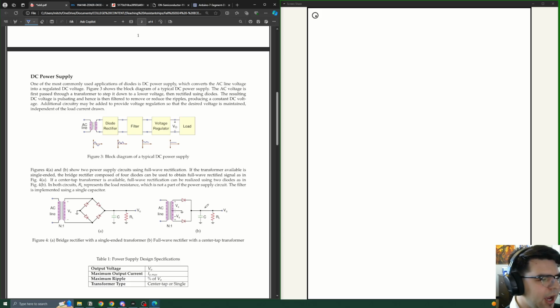And then we also have a center tapped transformer. That actually lets us reduce the number of diodes, because now we get this reverse polarity that we want. So when VS swings high, it goes through the diode to ground, and then it's already completed because ground is stuck halfway through here in the middle of the transformer.